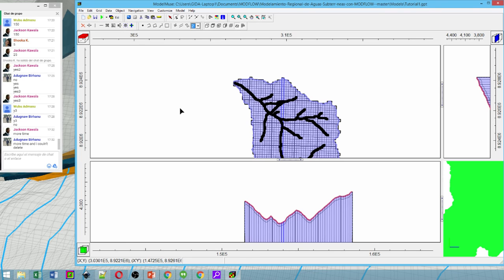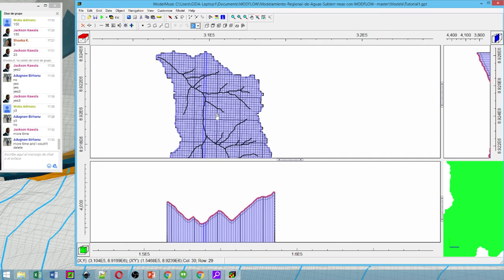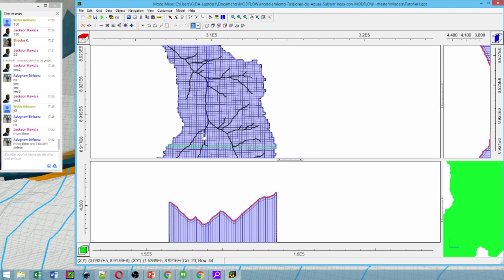Okay. While you are deleting, the next part: we unselect by just pressing the red arrow outside. We have to apply this element, this water network, as a drain boundary condition. If you remember, we have the drainage, recharge, and evapotranspiration. So what we are going to do now is to apply them.